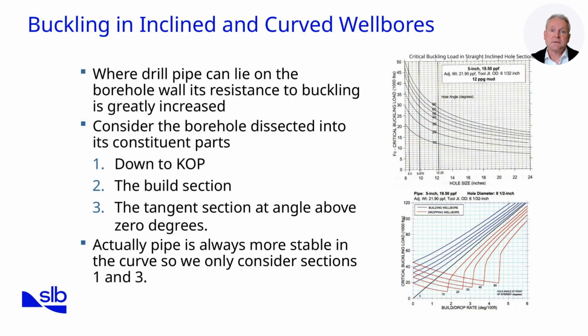The lower graph compares build and drop wellbores. Critical buckling load increases with build/drop rate, and the pipe is more stable in building sections, blue curves, compared to dropping sections, red curves. Engineers use these charts to assess safe operating loads.